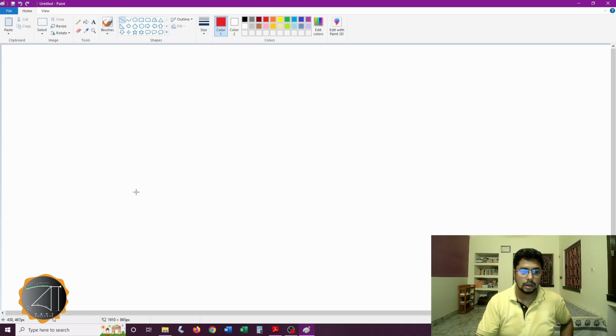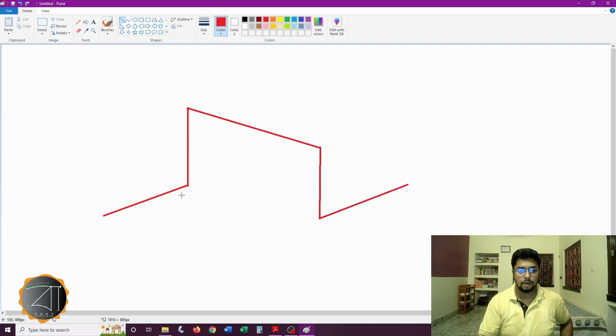Shear is a bar, typically bent like this. So starting from here, going up, turning to the right, getting down and bending into the opposite direction than what was the first direction of bending. This particular thing is provided to hold up the bars which are at the top portion.